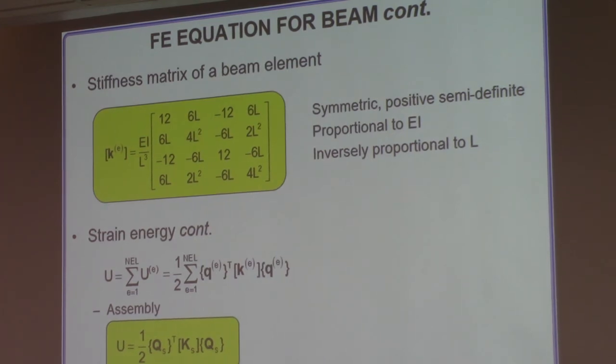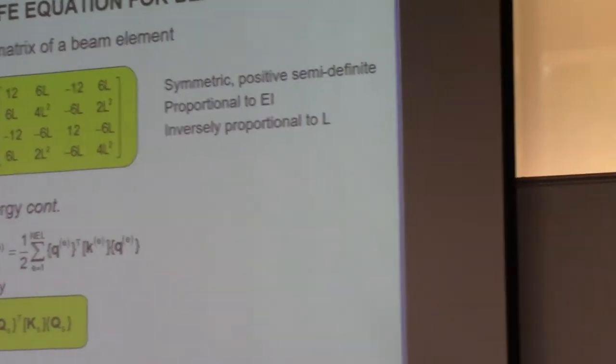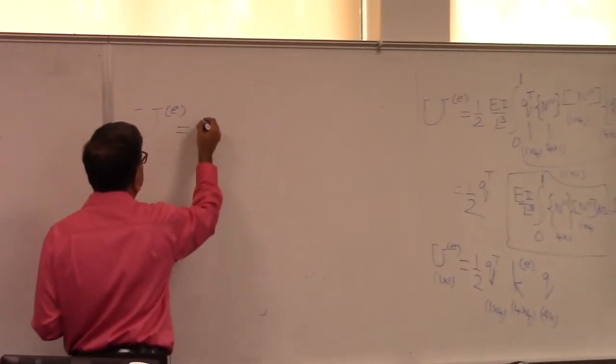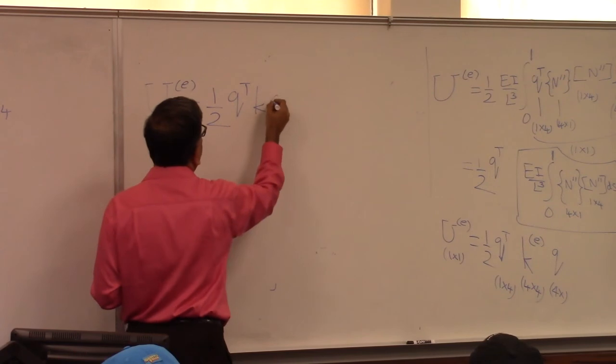Now if you found there's suddenly a new explanation, new meaning for element stiffness matrix. Take it from me, for all the elements in finite element method, the strain energy of the element, in solid mechanics, strain energy of the element is always given by 1/2 Q transpose KQ.